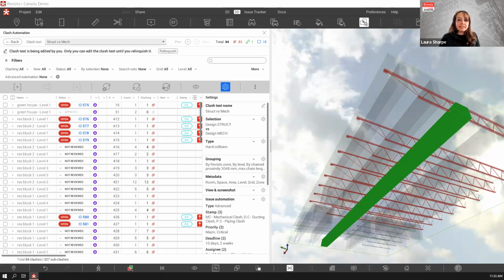In the design phase, and I'm going to speak about Revit because that's my background and most of my knowledge, phases do come in when you export from Revit, so you can turn that into a property condition in your search sets, and you could just search for phase 1 construction, phase 2. So again, all the power is kind of in the search sets and how detailed you want to make those.